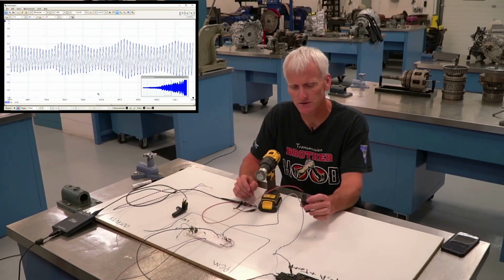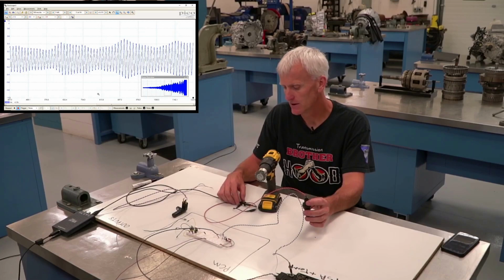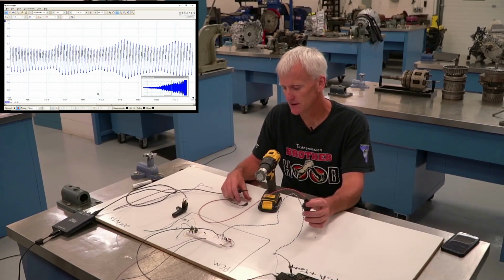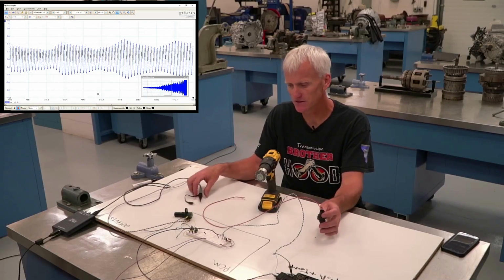So if you have 2 wires in a speed sensor, at least in a transmission, you can be pretty confident that it's a variable reluctance type. There are also 2-wire speed sensors called magnetoresistive, and they're different, but they're mostly used in things like ABS wheel speed sensors.